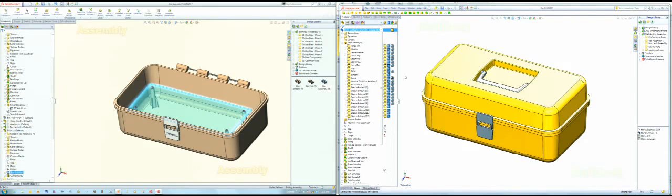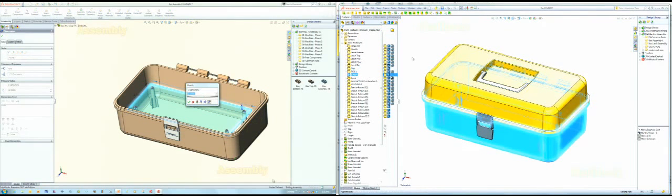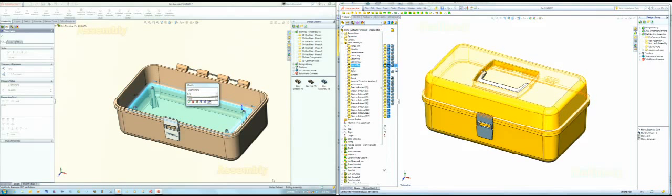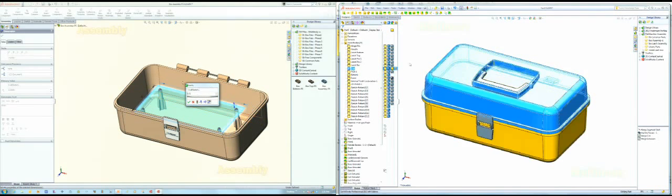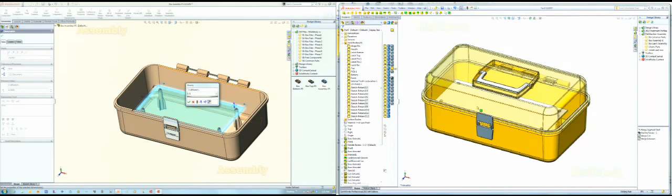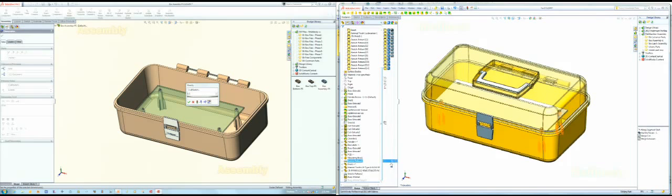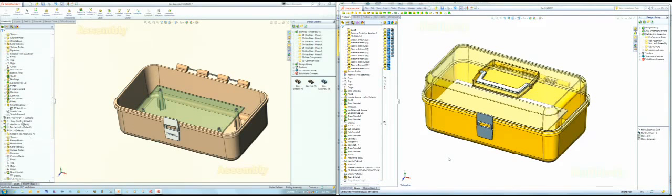And it's a pretty simple part. Right now it's 10 inches long, and we were going to bring it to something like 8.5 inches. So if I do that and rebuild it, the circuit board got smaller, all the mounting bosses moved with it, the hardware all moved with it, so that part's okay. The other thing we probably need to do is change the size of the box just to make sure it follows along as well.